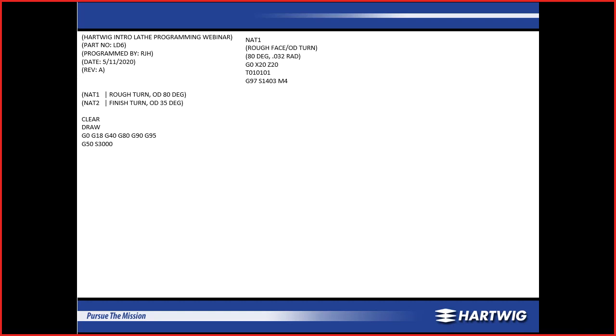So we're turning on the spindle to 1403 RPM in the counterclockwise direction, meaning my insert is going to be facing up and my tool nose is facing to the left to get ready to turn my part. The reason I'm using the speed 1403 is because at the diameter I am turning on constant cutting speed, this is what the calculated RPM would be. It'll save a couple seconds of cycle time so that the spindle doesn't have to ramp up or down when G96 is commanded.